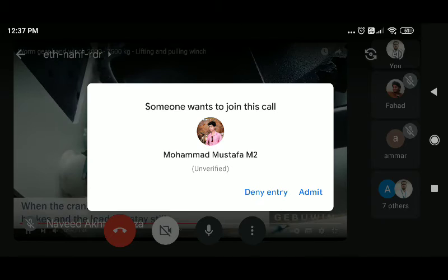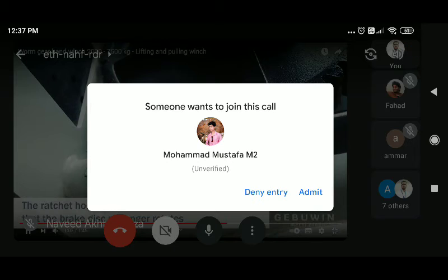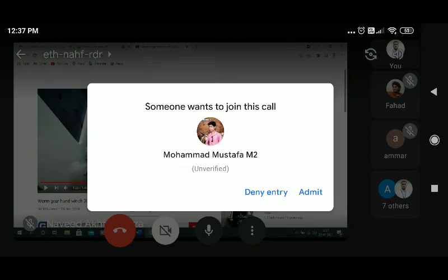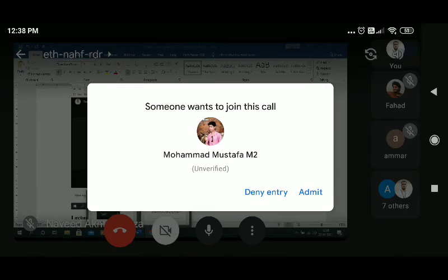Now it is stopped. The lock is there. You can see the ratchet hook behind the ratchet wheel. So the return movement will not happen here. It is locked. That's why the worm and worm wheels are used in practice, okay, for lifting the heavy load. So you understand this better. So this is the application of your worm and worm wheel.